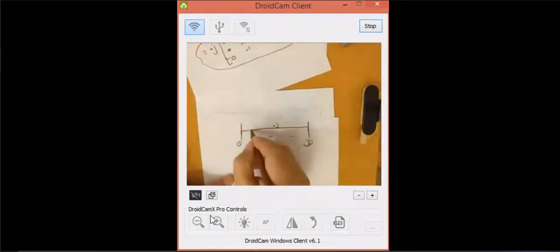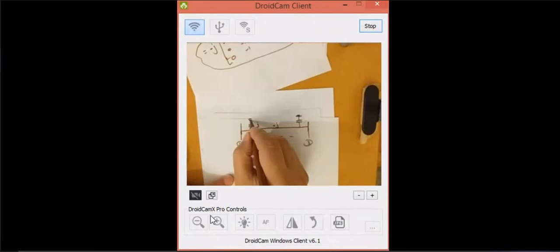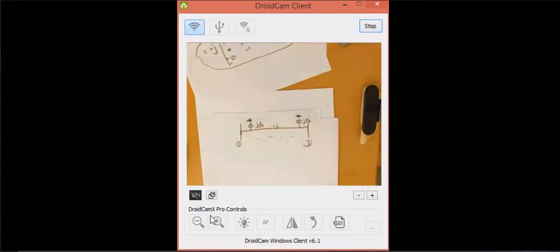It is a medium transmission line, so this is J and this is J over 2, and the total shunt is equal to Y. We represent a medium transmission line by the pi model. So we use Y in the line, Z in the line, and Y divided by 2 here and Y divided by 2 here.